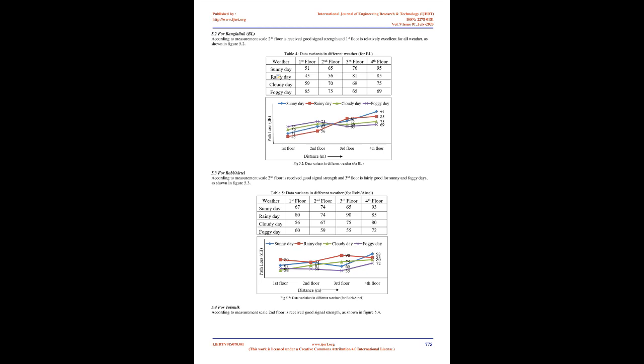4. Signal strength and measurement. In telecommunication, signal strength refers to the transmitting power output as received by a reference antenna at a cell phone and/or cell data device, which is a radio. Radios operate on signal strength and signal quality. These are both measured in decibels, dBm. Decibels are expressed as a negative number, like -70 dBm. The closer the number is to 0, the stronger the signal. For example, -70 dBm is a stronger signal than -90 dBm. A front panel LED on the CDI device is used to flash a number of times to indicate the signal strength as per the table below.